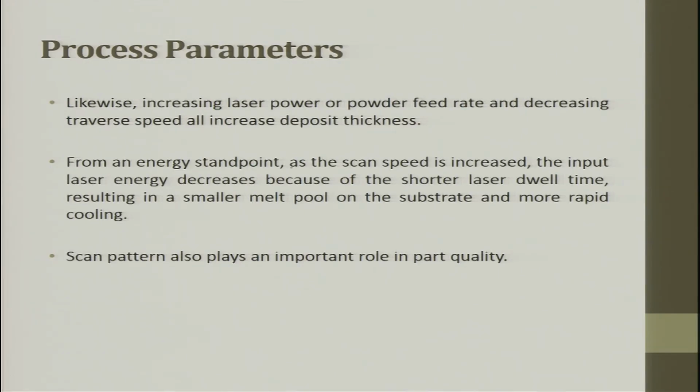From an energy standpoint, as the scanning speed is increased, the input laser energy decreases because of shorter laser dwell time, resulting in smaller melt pools on the substrate and more rapid cooling. So, basically when you scan quickly, it is a fast movement and the laser interacts with the material less. So, a low amount of energy is applied on the surface, giving a low melt pool. This will try to give you thin layers, or it might produce defects.